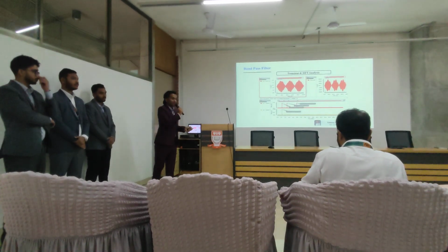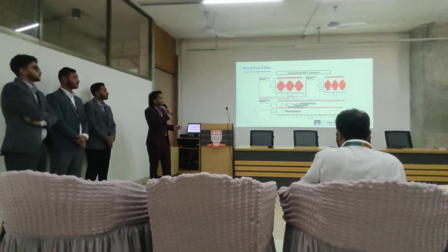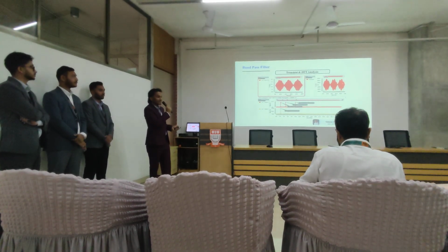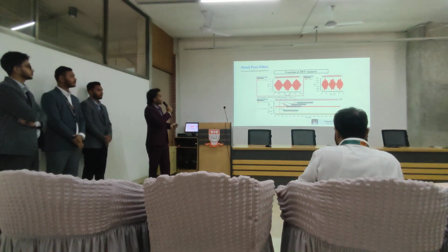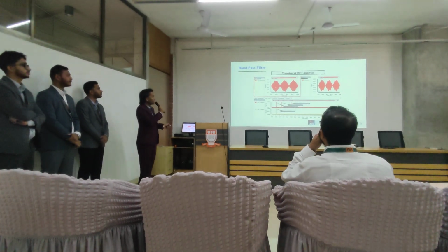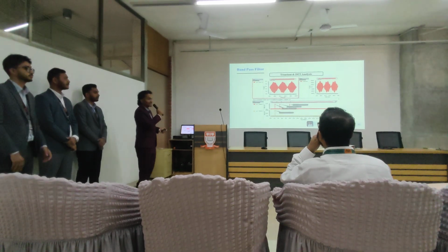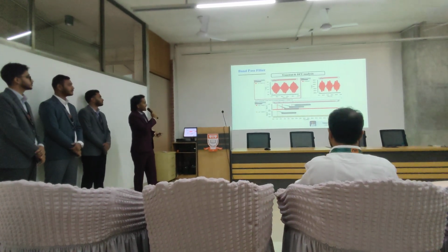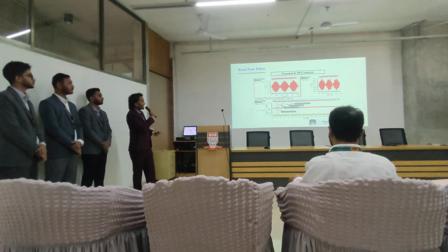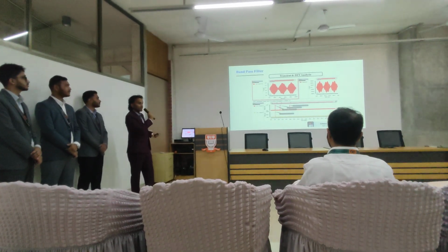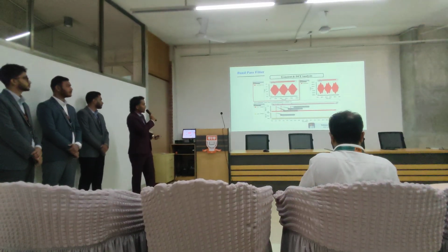Then to show our bandpass filter only allows 2.45 GHz, we have used three frequency components here: 2.45 GHz, 5 GHz, and 10 GHz into the input, and in the output we only get 2.45 GHz. But it is still not clear, so we have used DFT analysis. Here we can see the three frequency spectrums: 2.45 GHz, 5 GHz, and 10 GHz that we put into the input of our bandpass filter, and in the output we only see 2.45 GHz.